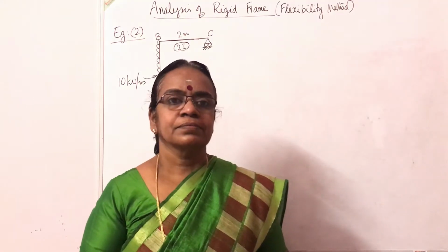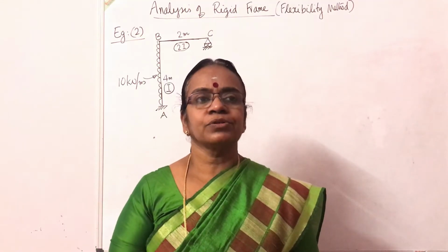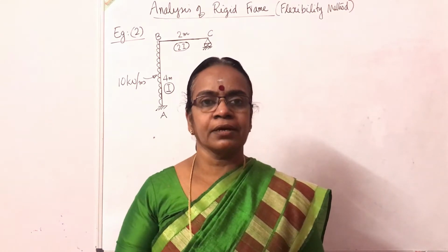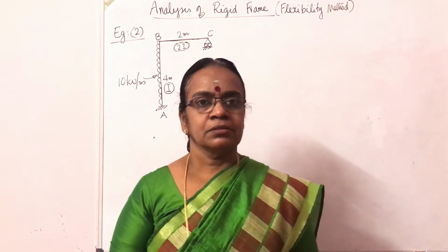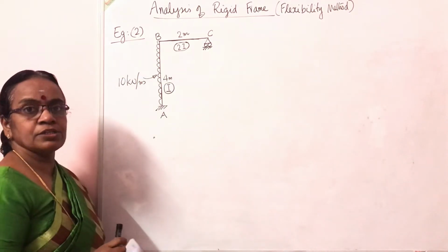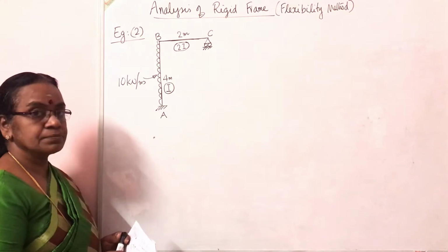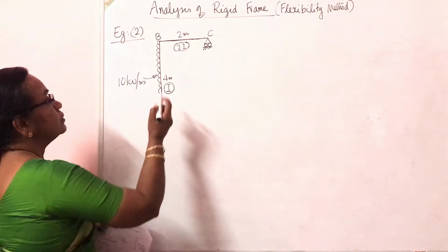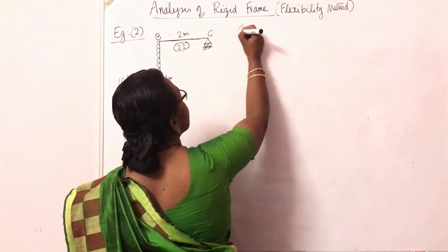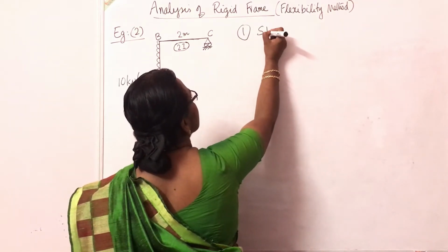Good morning. I'll pass on to the second numerical example in rigid frame analysis by flexibility method. Let's consider a rigid frame as shown in figure. So first step in flexibility method is always identify the static indeterminacy.